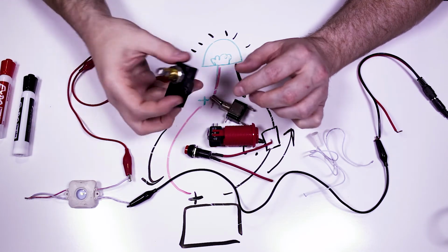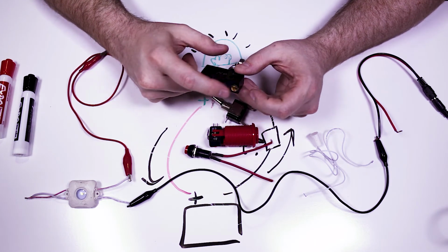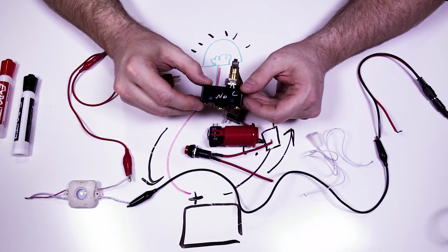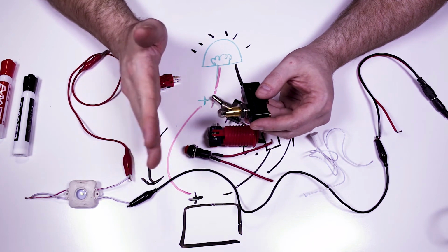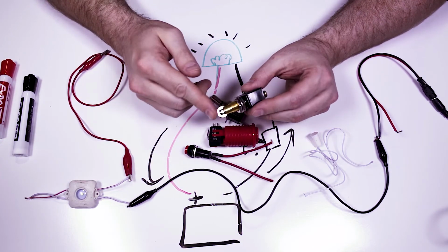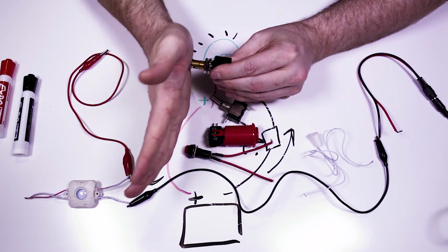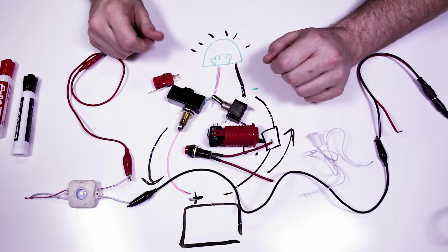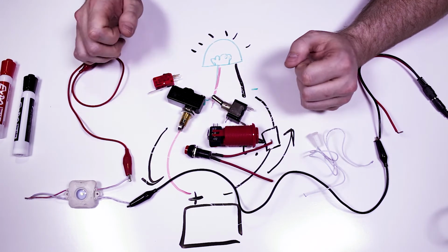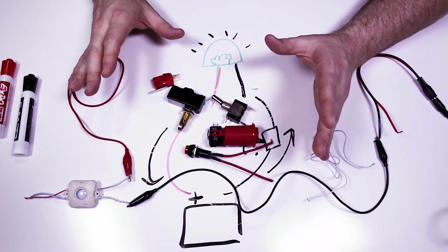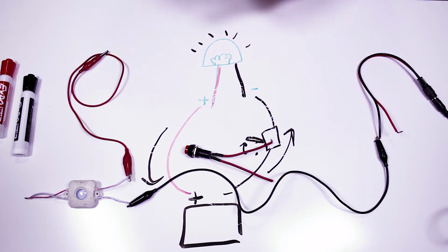And then here's a weird little switch here. This one's very interesting. This one actually has normally open, normally closed, and common as well, depending what you need. But this is kind of a limit switch. A limit switch is when something reaches a certain limit, it causes something to do something. And this has a roller on it, so something can roll across it or on it and disconnect or connect it like this. So all of these are switches, and there's many, many other kinds of switches out there. Relays are switches, and I said RFIDs are switches. Pretty much everything's a switch. But we're just going to deal with the very basic switch here, like this.